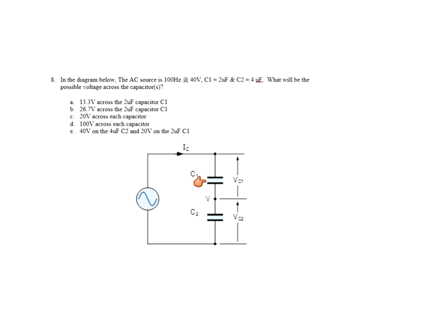That's a smaller voltage, so I don't want that one. What about this one, 20 volts across each? The voltage won't be the same on each of these because they're different microfarads. Different microfarads will give you different voltages. That still doesn't answer the question about the smallest cap with the larger voltage. 100 volts across each, no. Well, first of all, the voltage won't be the same, and second of all, you only have 40 volts applied, so that can't be it.